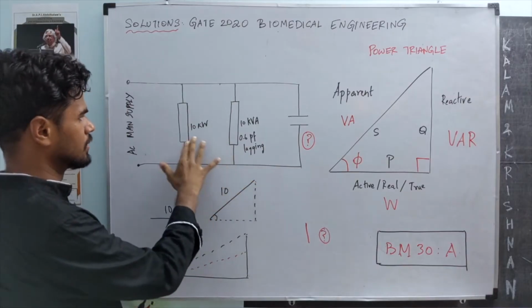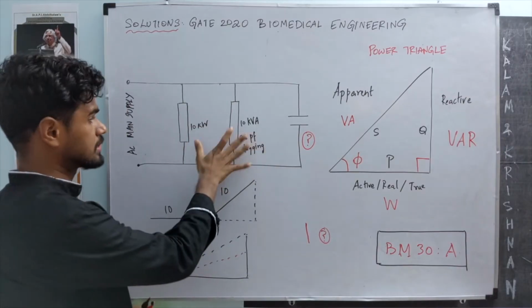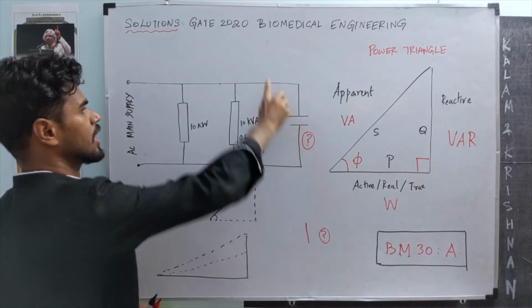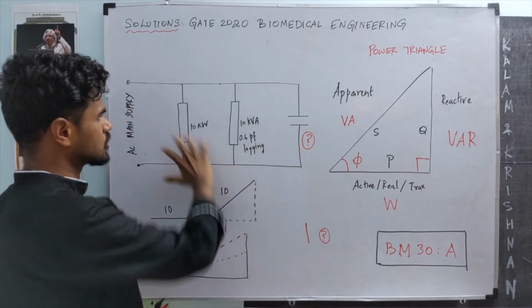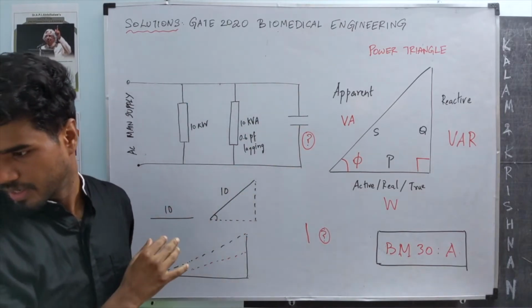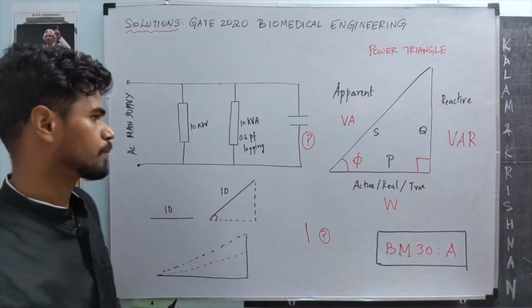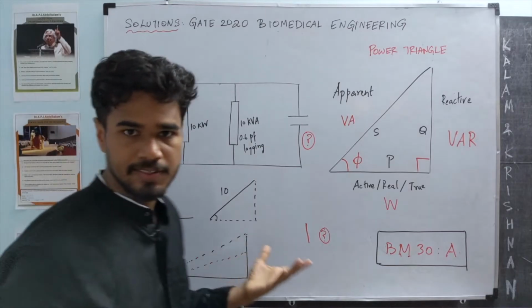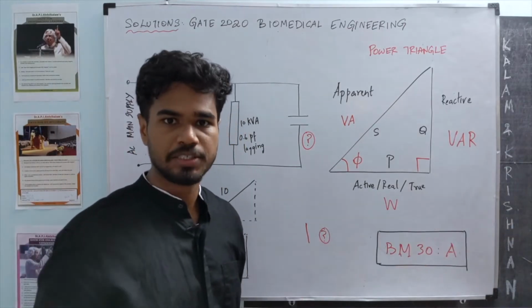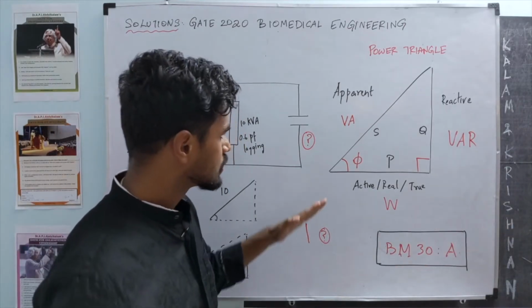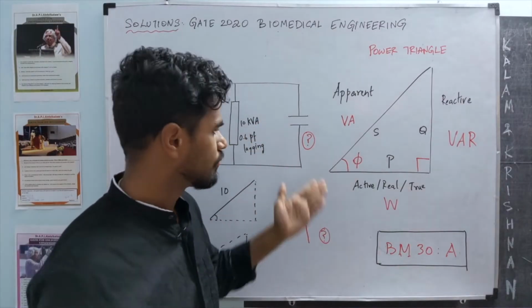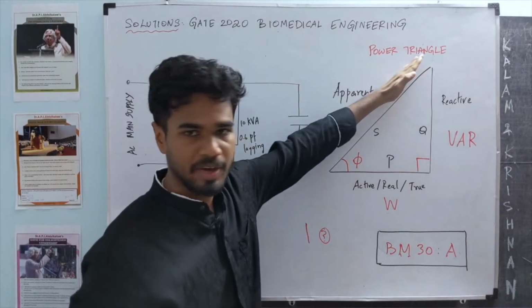Let me explain what this is in a moment, but we want to add another capacitor to this so that we end up with the overall power factor of this being 0.9544. In AC circuits the voltage is not in phase with the current, right? So just the product of voltage and current, that's known as the apparent power.